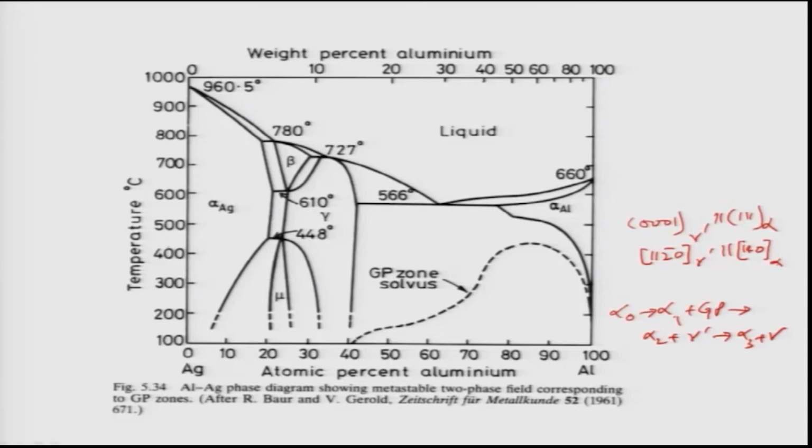But as you see here, these alloys can actually be used at a little higher temperature than the aluminum copper alloys, because the solvus which is shown here can go up to 550 degrees Celsius. So the treatments will remain the same. Again, you take any alloy, heat it up above the solvus temperature, followed by quenching, and then one can do heat treatment at different temperatures, either here or a little higher depending on requirement.